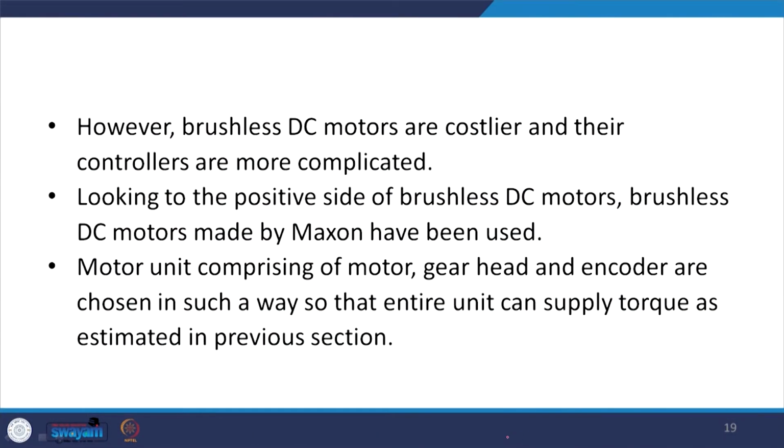Now, these brushless DC motors are costlier and their controllers are more complicated. So, that is one problem with them. But looking at the positive side, we have used brushless DC motors made by Maxon, and this motor unit comprises basically the motor, the gear head and the encoder. And these units were selected such that we get the required torque.